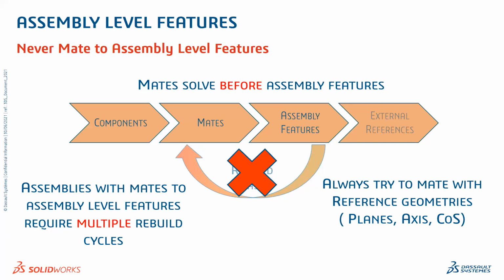When you are referencing into any parts or any other surfaces or any edges, whenever we are rebuilding it, we are going to face challenges. So always, or whenever possible, try to mate with the reference geometries like planes, axes, and coordinate systems.